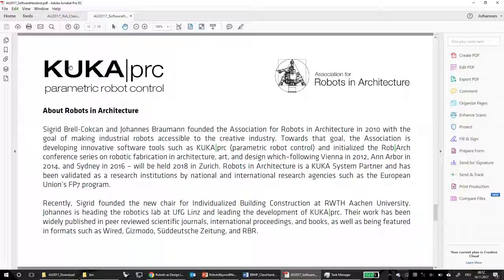But if you want to do really high-end milling and you have the money, then of course it makes sense to go for a 5-axis milling machine. For us, something that's also been quite important, depending on the setting, is transport. That might sound silly, but if you want a machine to build something very big with a gantry machine, your machine is going to be larger than your workspace. With the robot, you actually have a rather compact machine.